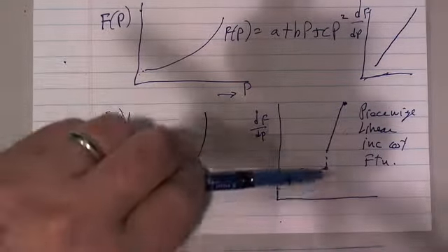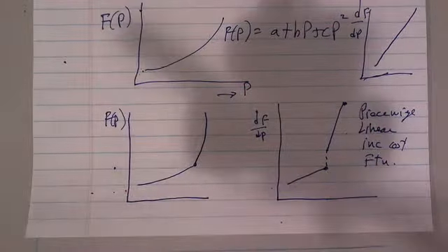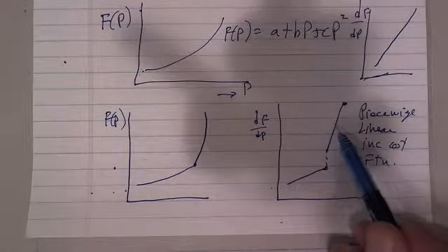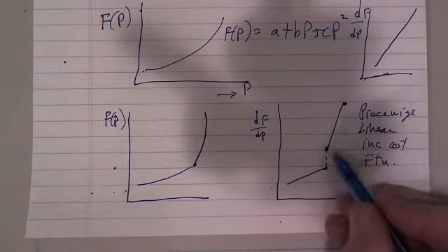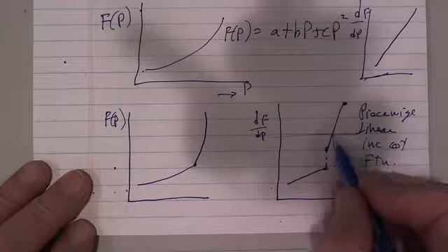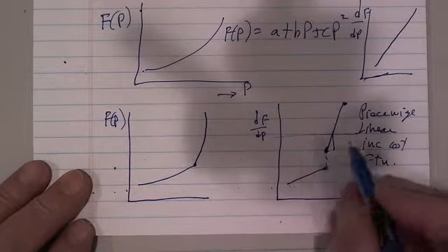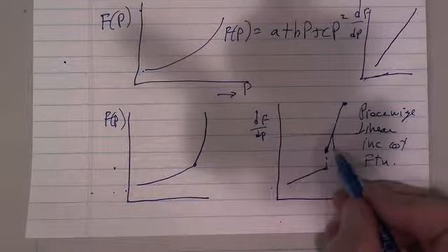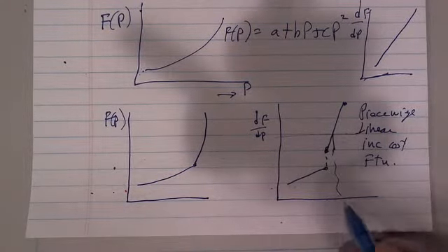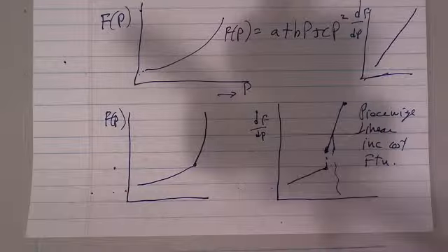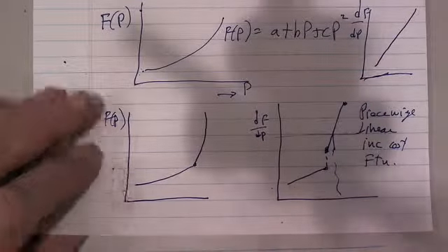That lambda search technique works beautifully on piecewise linear because you come in with a value of lambda up here, and it's just a matter of proportioning. If I came in with a value of lambda like this, and I know the point down here, then the intersection I can calculate because I have the slope. I can calculate the new p over here very quickly. So it's just a couple of multiplies and add, subtract, and it's done. No quadratic or anything to solve.